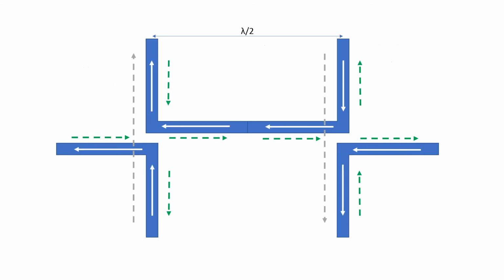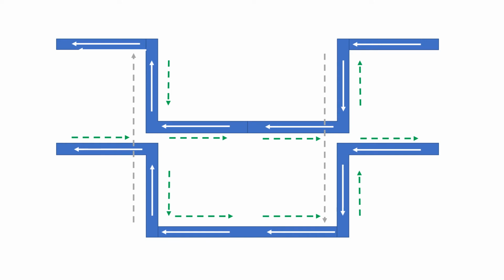The empty space can be filled by a twisted dipole antenna located half a wavelength away from the first. But it must be reversed to create constructive interference, due to reversed polarity in that location. The antenna array can then be completed and repeated in vertical and horizontal directions to cover a larger area.